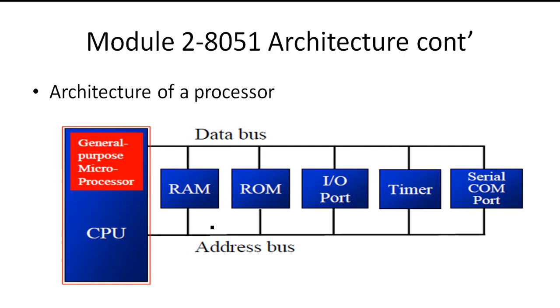The address bus is nothing but some lines from the microprocessor that go to all the internal or external peripheral devices to address each of them. So each address will be unique, and we can change the access to different external devices by simply changing the address lines configuration. Depending on the number of lines on this address bus, we have microprocessors ranging from 8085 to 80486 and Pentium, then higher end.